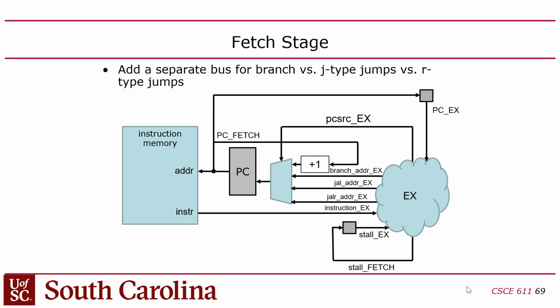And for whatever reason, when I used to teach this class in VHDL, if you did that in VHDL, ModelSim would say iteration limit reached, 10,000 iterations, bailing out. But in Verilog, it doesn't have that iteration limit for some reason, and it just locks up, it hangs. I don't know why, because it's pretty much the same idea, but it'll lock.